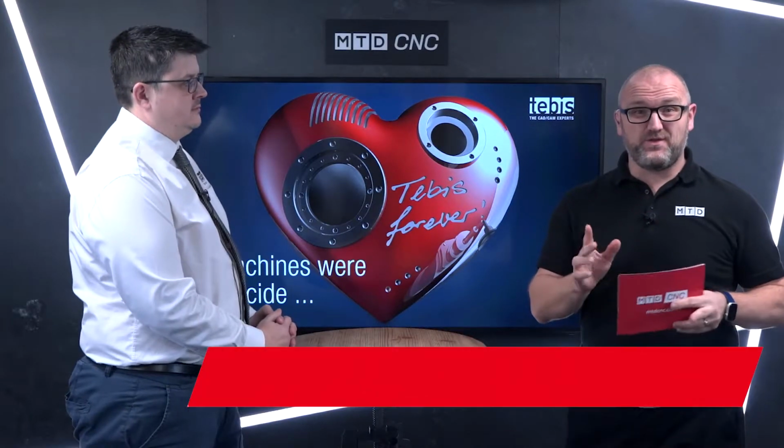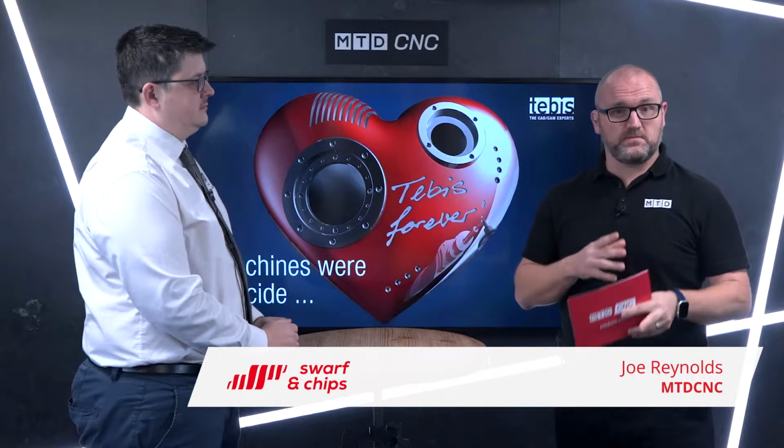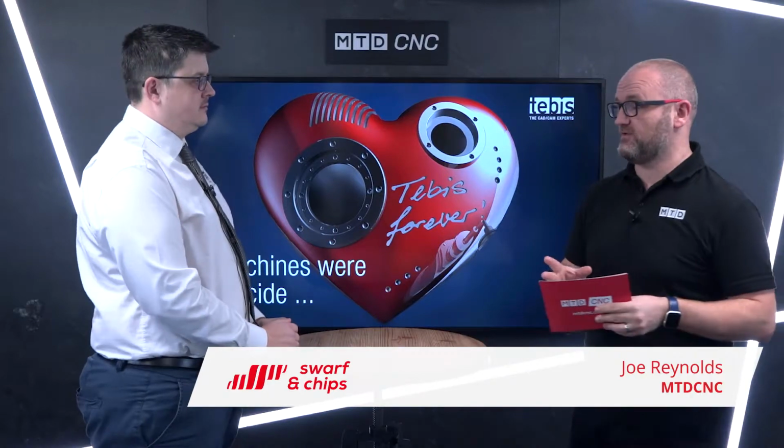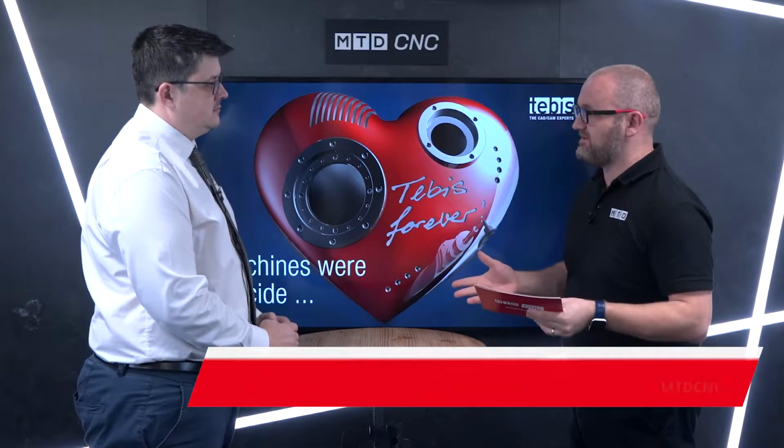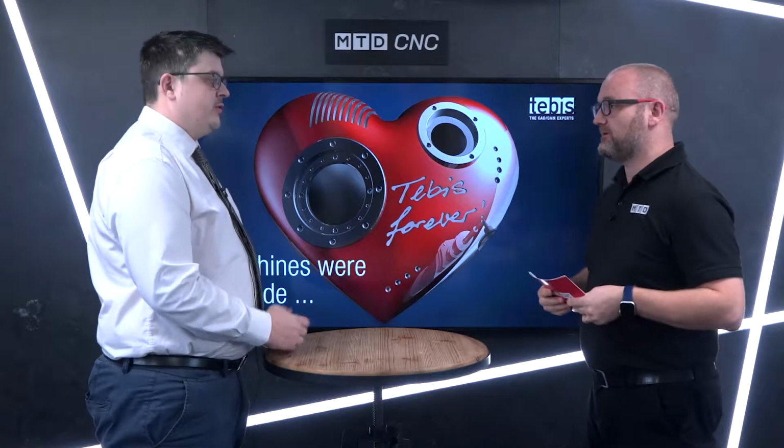Do not go anywhere. In this short video, we're going to be talking about some of Tebis's CAM solutions. And the first one I want to talk about is the feature side of things. So what is it and how does it work? For Tebis, features is basically a way of recognising CAD data within the model. Once we've recognised this CAD data and assigned some basic parameters to it, we can then add predefined machining operations to it and use this to drive our programming process.